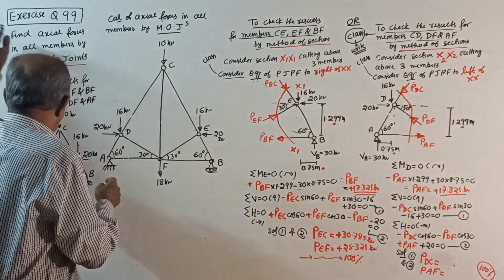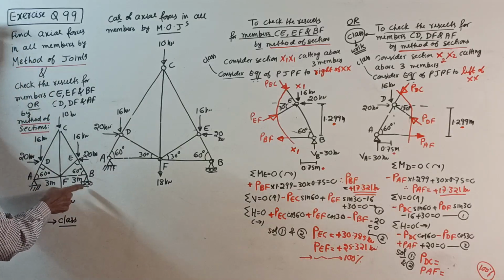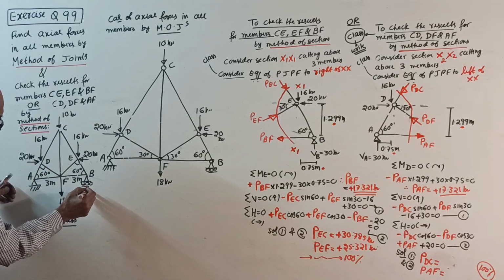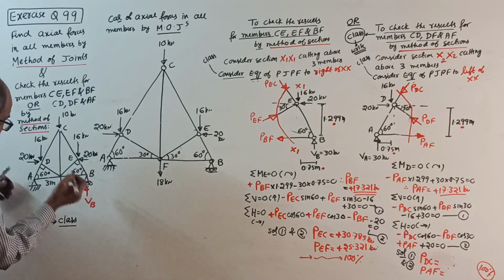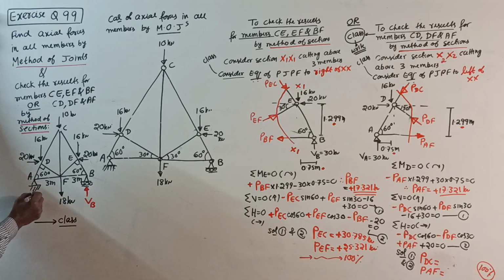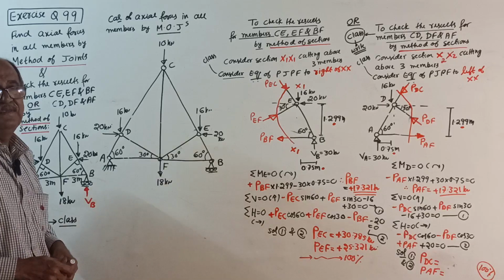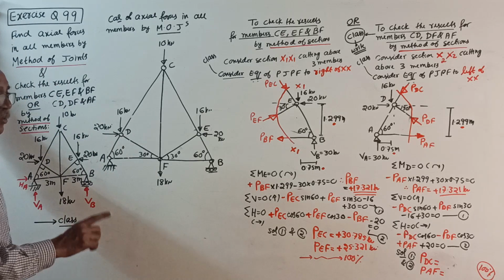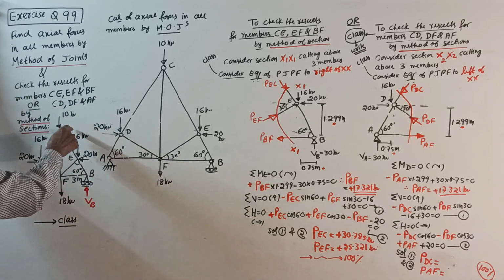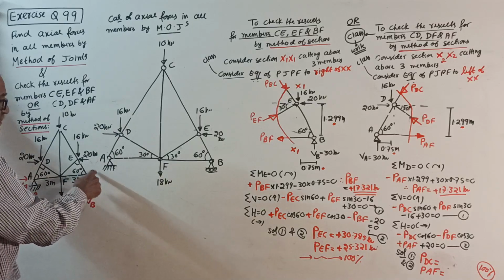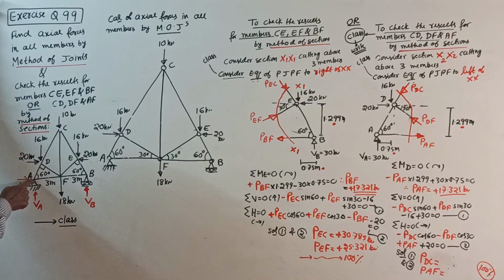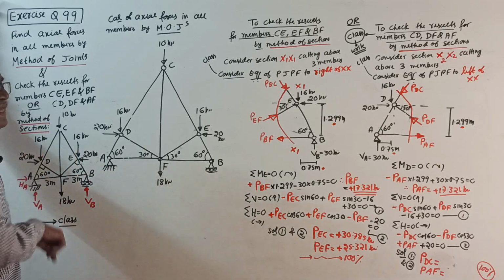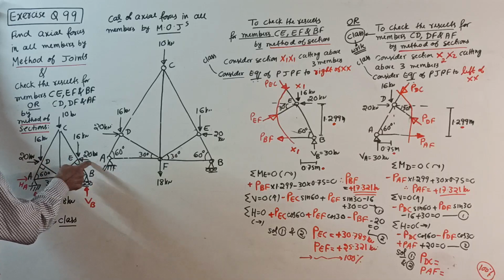Then, so one hinge, one roller. Roller has got only, see, vertical reaction, VB, I will put here now. Hinge has got vertical reaction, VA, and horizontal reaction, HA. Then some will tell, this already told, loading symmetry is there, reaction symmetry is not there. Then, see, there is no horizontal reaction at B. Horizontal reaction possible only at A. But here, 20-20 balances. See, net horizontal force equal to 0.